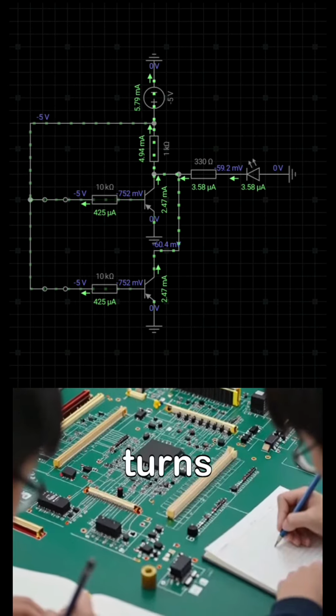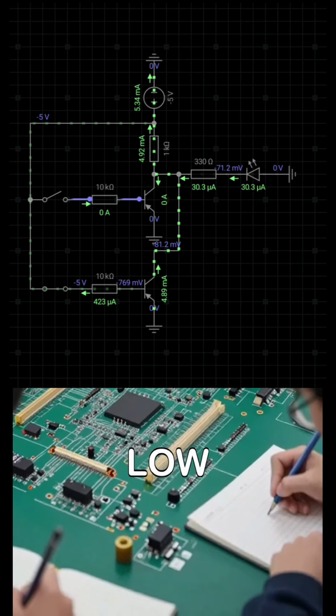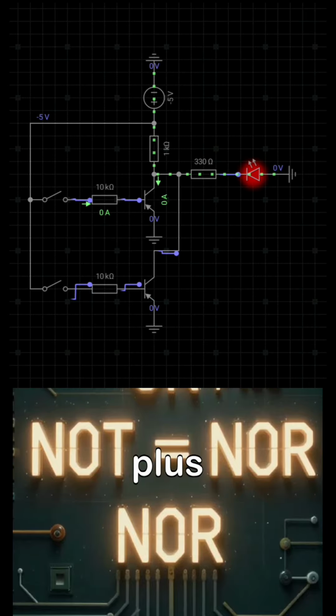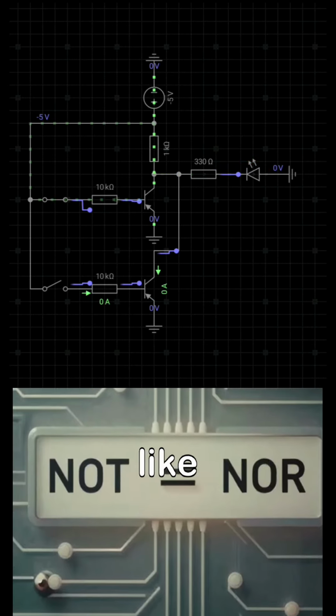The LED turns off. Because any single high input forces the output low, this is an OR action followed by inversion. OR plus not equals NOR. That is why this circuit behaves exactly like a NOR gate.